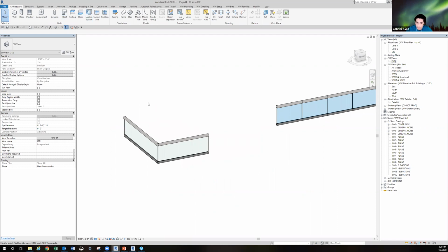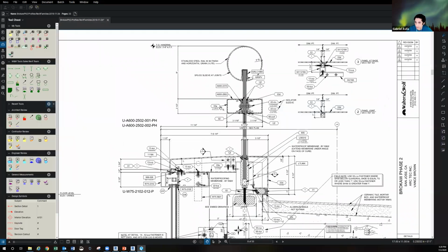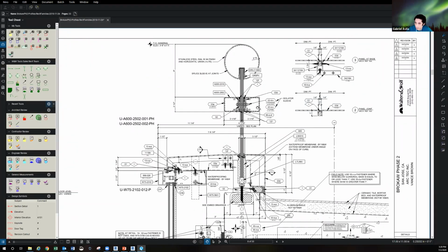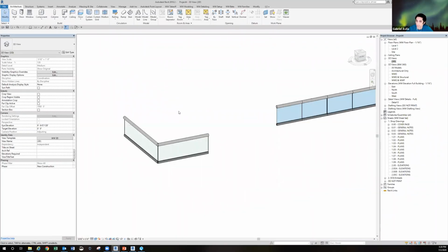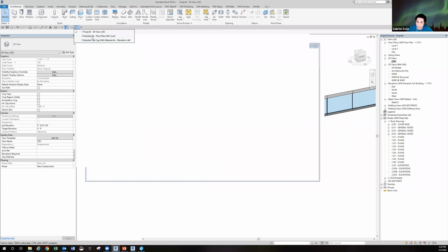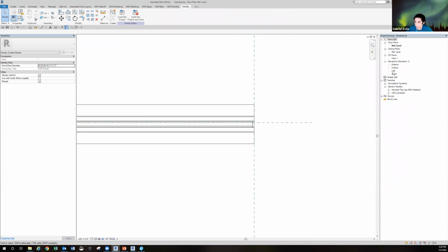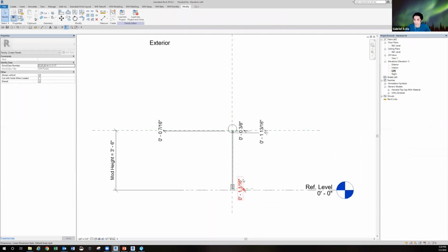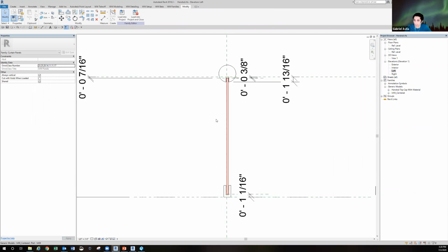And then let's go back to the family, and I want to modify it to look like this. I have a little cover here, a little extrusion. So how do we do that? There's two ways. You could make it outside like the top rail cap, or you can make it inside the family in this left view and lock it in place. Either way works depending on how you want it to look or behave inside the family. Let me just make it in here.